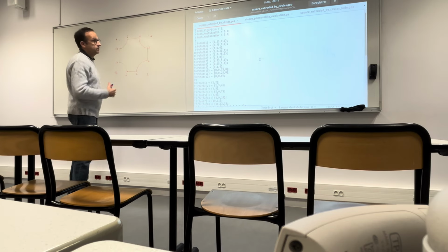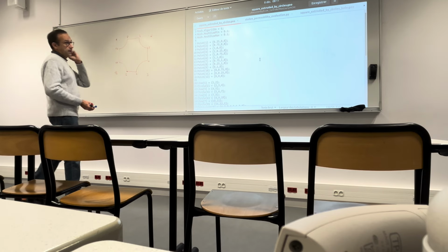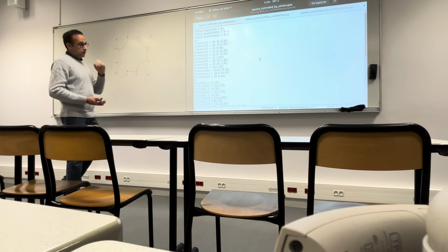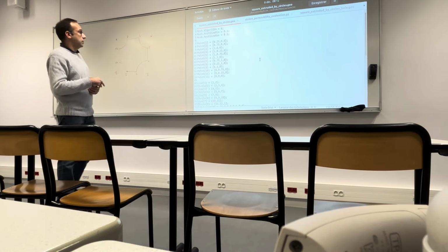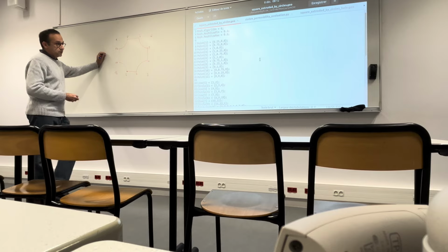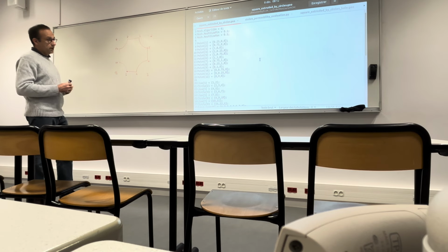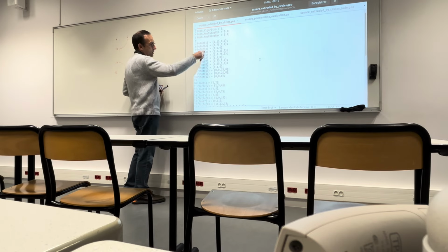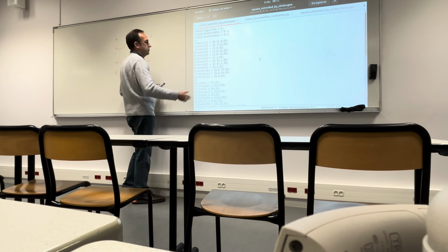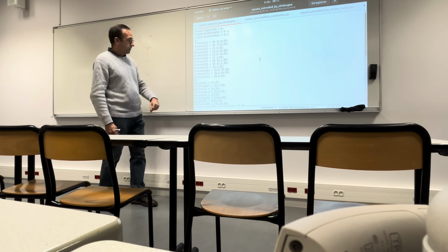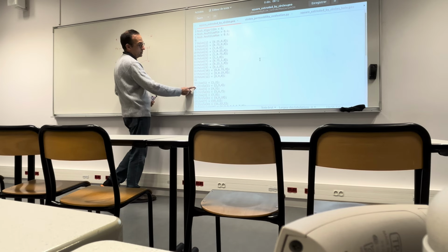This is just because of the syntax of this geo file, which is the input file of the GMSH software. So you have to provide them as 3D points. Then we will remove the third coordinate in the Phoenix code. And then notice that you have to label each point and then each line and so on. So you have point 1 to point 12, then lines, which are lines and circles.